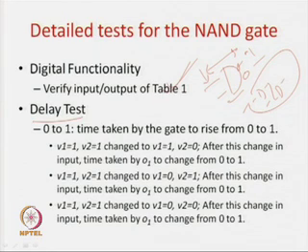But in the case of a VLSI circuit like a NAND gate, digital functionality is one, and the other very important test is the delay test, because unless you say what the time required by this gate is, nobody is going to accept the design. When someone plugs your gate into his circuit, he should know the amount of time the gate requires to give the output. Accordingly, he can go for his design, because when he ships his product, both his digital functionality as well as your performance in terms of speed are very important.